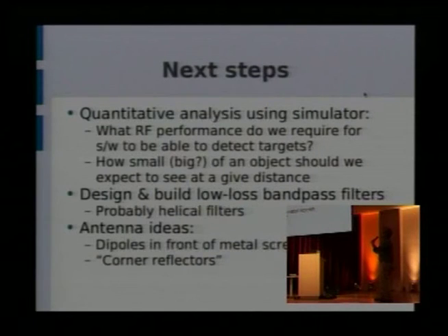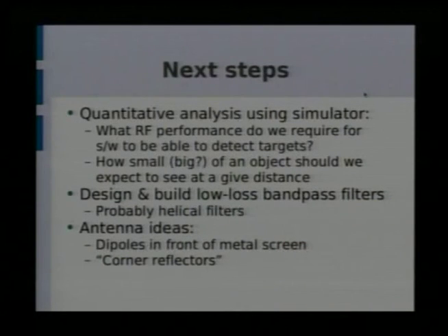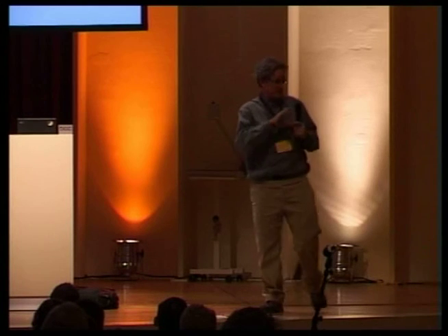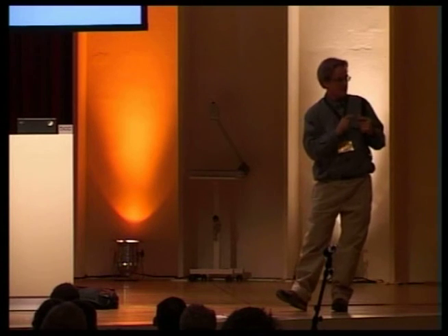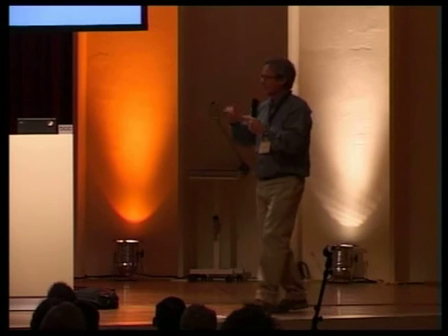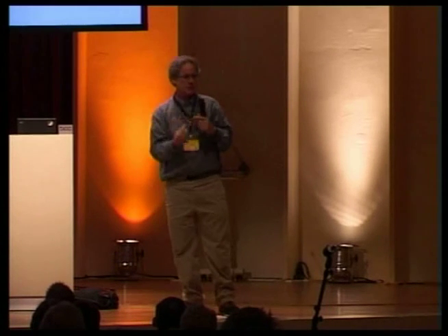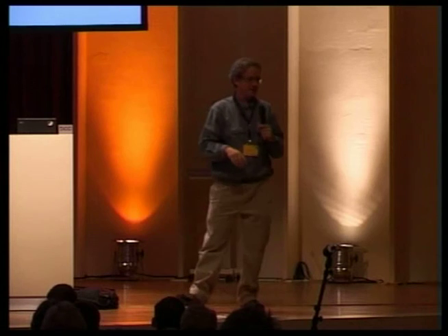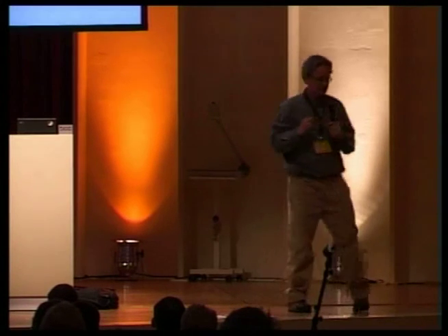My friends who are real RF experts keep telling me, you need helical filters. I'm like, okay, I'm looking for people who want to build helical filters. Those are actually a very cool mechanical engineering hack. They like to do them at 100 megahertz. They end up being about 10 centimeters across and 5 centimeters tall. It's a piece of copper pipe that has a copper helix inside of it that only has one end connected, the other end freestanding, and it works because of the mechanics right inside of the thing.